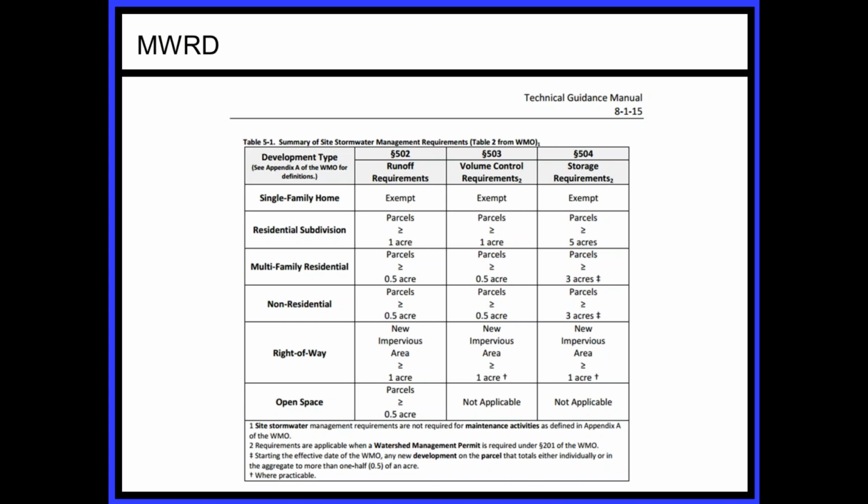And then in addition to that, storage. If you have a condition where your downstream storm sewers cannot accept a lot of water, you have to hold that water. You have to attenuate it and give it time to sit until the rain event is passed, and then it can be metered into the system so that you're not surcharging your existing systems. So for example, if you look at a traditional application for stormwater management, a non-residential environment, almost any site has to have all 3 of these, or all 2 of these controls. And certainly if it's a larger site, which a lot of large developments are, you're going to have all 3.